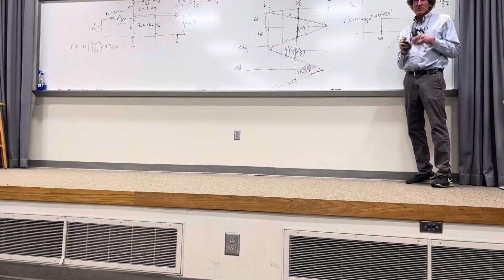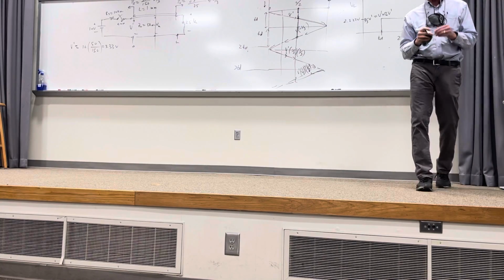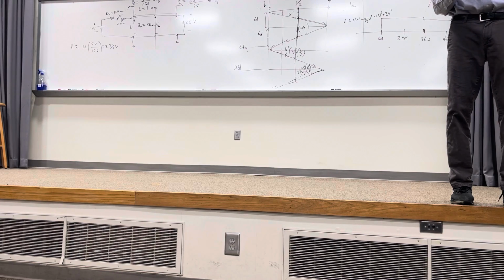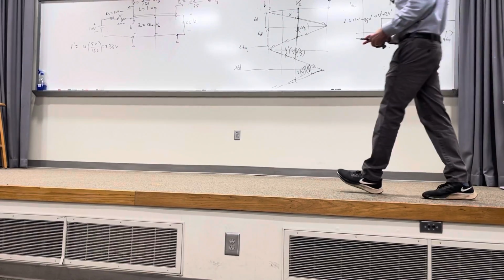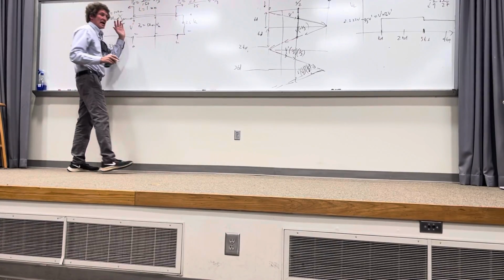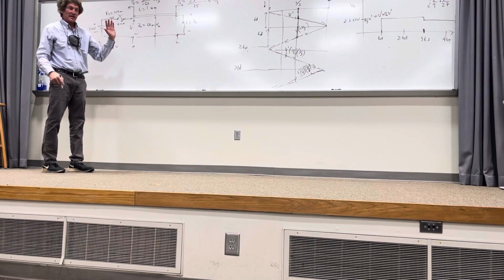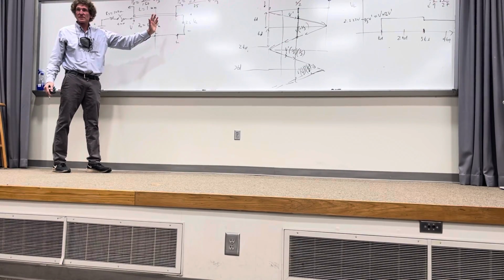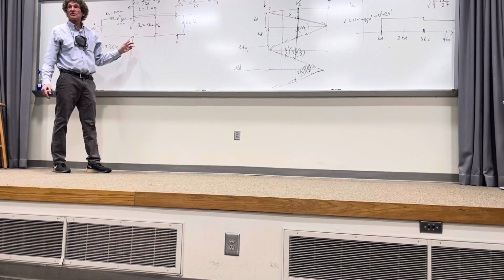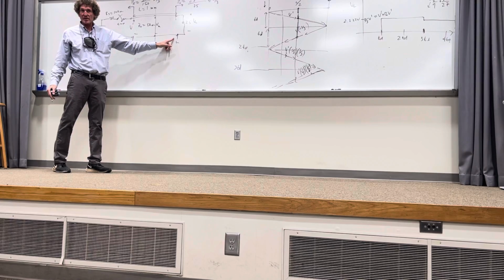Now, by this time, most of you see that every bounce reduces the amount of change. As time goes by, what your mind tells you, it's going to settle to a constant value on the line, and that's absolutely true. And this is the point I want to make next. When I take a look at this transmission line, as time goes to infinity, all these bounces just die out to nothing. And this transmission line looks like just 2 pieces of wire that are connected at a very short distance.